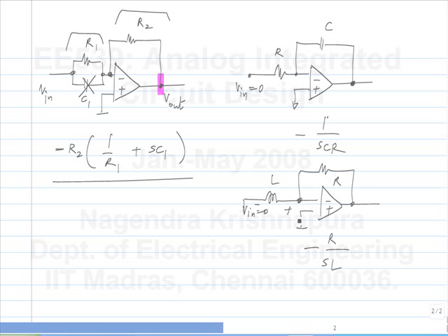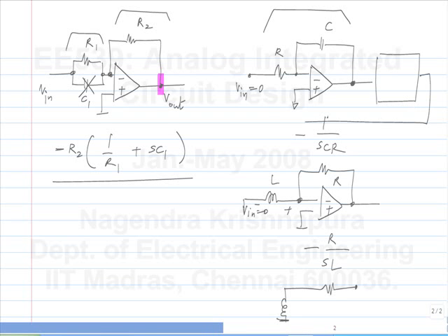What is the DC gain of the feedback network? The feedback network is this one, right? So there is no DC negative feedback here either. So you can't make these circuits, at least you can't make it in this form. Perhaps you can get this, you of course use integrators and filters and so on. So what happens is there will be some other network which probably has some feedback to this point, which provides DC negative feedback. Just by themselves you can't make these circuits, because it won't get biased properly.